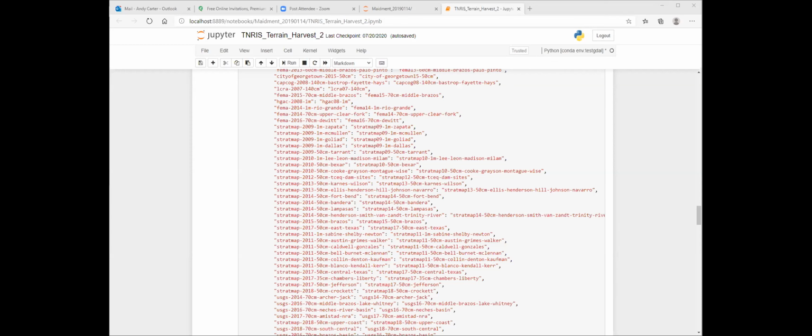Cool. So this is Jupyter, and I'm not going to get into the nitty gritty as to what Jupyter is, but Jupyter is kind of a web interface to run Python scripts. So this is me playing with Python to get certain things to work. I'm going to do a blog post in about a week or two, when I can get to it. What this routine does is exactly what Adam is doing manually. The intent is you load in a shapefile, and once that shapefile is loaded, it automatically goes to TNRIS data, which is on an Amazon Web Service. It downloads everything that you need in the area that's requested, whether that's 1 tile or 500 tiles, unzips them, merges them into one surface, and then clips and buffers it to the boundary of the requested area. So if you need an entire watershed, like Walnut Creek's watershed, or if you just need the site, it'll make that sample.